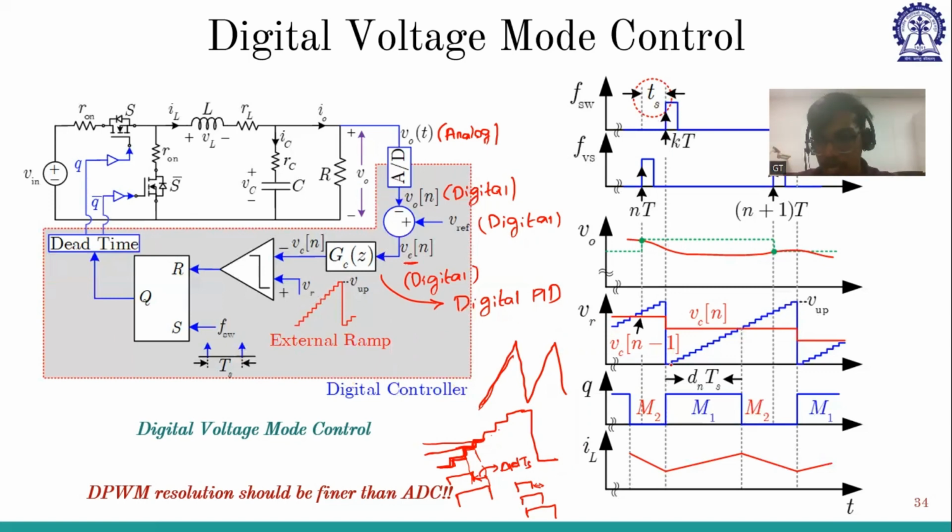Now, see, this is the counter. This is the switching time TSW, and each horizontal step has T clock. The clock frequency will decide each step. Now how many steps are there? The number of steps is TSW by T clock. If you want finer resolution, if you want to reduce this delta D, you have to reduce this T clock time.